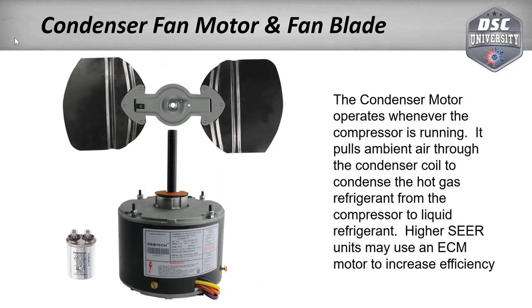Condenser fan motor and blade. Like I said, most all our condensers, except for the 20 SEER units and maybe a couple of other models, all the condensers and heat pumps are going to have PSC fan motors, which means they run with a capacitor. It's a direct drive to a fan blade, so nothing really fancy there. This is actually upside down. All of our fan motors are mounted in there hanging with the shaft down. If you pop this little plastic cap off, there are 4 screws that go into the butt of that motor and just hold it to the grill.